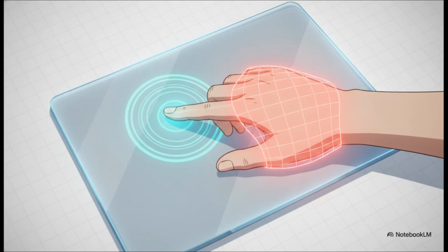But of course, we don't just point at our screens, we type. We rest the heels of our hands right next to this incredibly sensitive grid. So to stop your resting hand from causing absolute cursor chaos, they use these sophisticated palm rejection algorithms that run constantly in the background. They filter out those unintended contacts using specific size and pressure thresholds. Basically, if a contact shape is too wide or it lacks the dynamic pressure variation of a moving fingertip, the system instantly flags it. It goes, "Oh, that's just a resting palm," and completely ignores it.